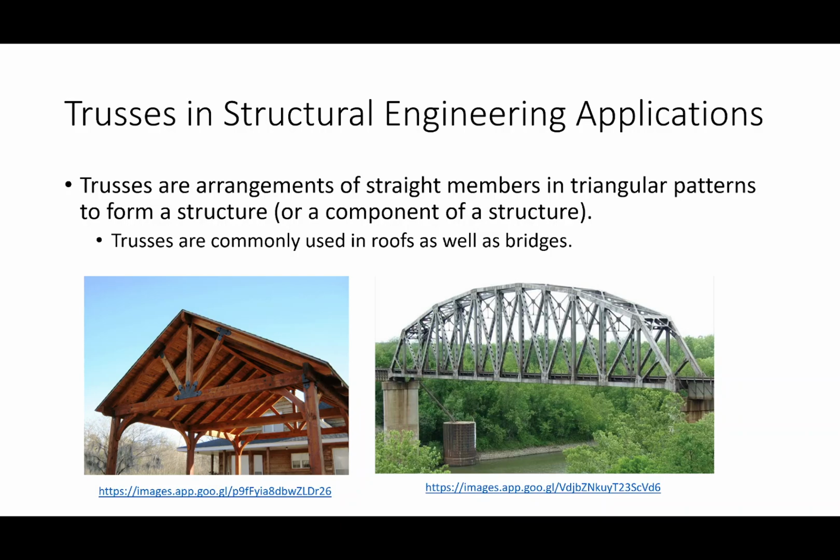That's one upside. Let me mention another upside. Trusses are light. If you compare, let's take this bridge right over here on the right. If I were to replace this bridge with a comparable beam and slab system, there is a very good chance that system would be heavier. Trusses are light and they're stiff. One of the downsides of a truss, though, is that it's expensive.